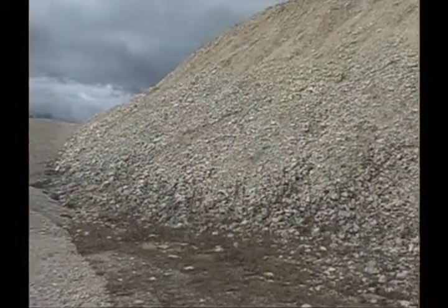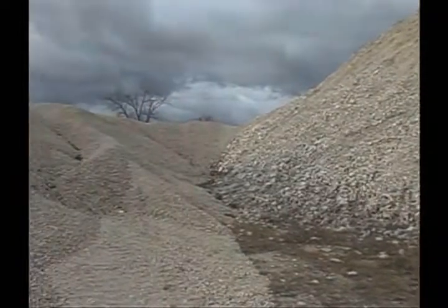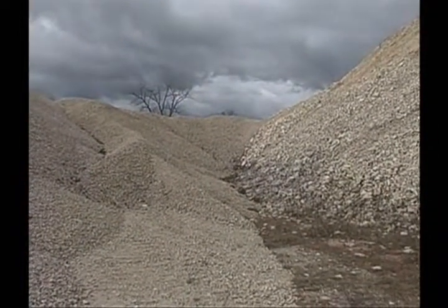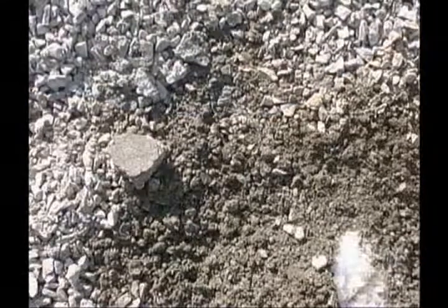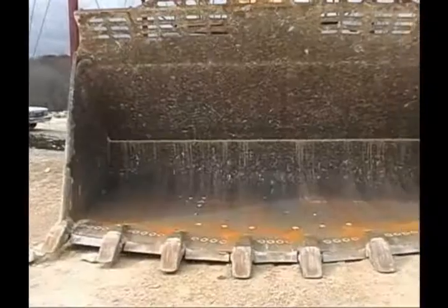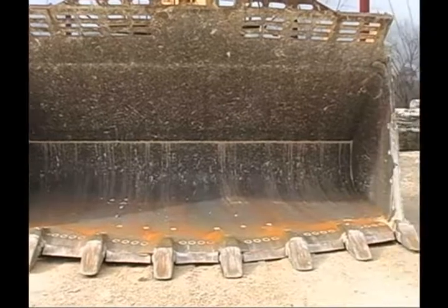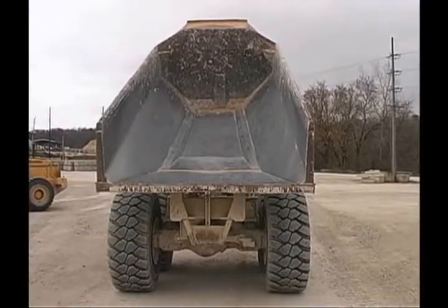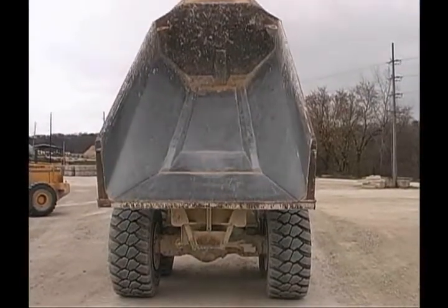Degradation is the breakdown of the material. If ramp areas are present in a stockpile, this material should not be incorporated in the finished project. Mingling of stockpiles should be avoided, as this procedure could contaminate the product with non-complying material. Deleterious materials such as mud, clay, dirt, or other foreign material should not be allowed in the stockpile. Be sure loaders and truck bodies are clean and free of these materials when building stockpiles by these methods.